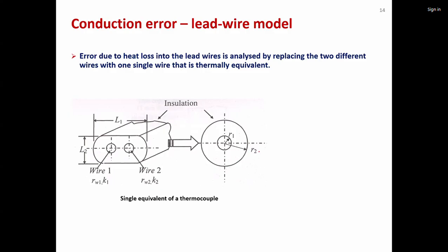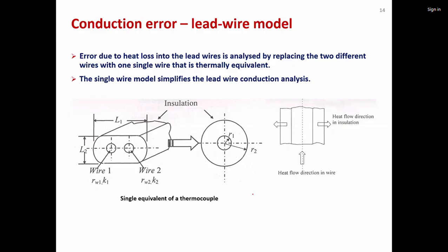Okay. So in this situation, we have simple formulas to do a heat transfer analysis of this kind of cylindrical arrangement. But for this complicated geometry with a flat top and bottom and curved sides, we cannot do a heat transfer analysis. So you build a thermal equivalent of this system. When you do a thermal equivalent, there are certain things you have to preserve. We talk about what we preserve in the next slide. But before that, this is what I wanted to talk about.